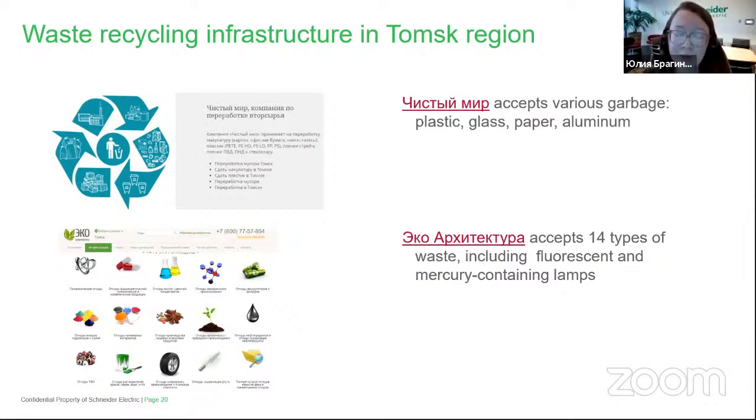And I want you to know that the fluorescent lamp is hazardous waste, which is classified in Russia as first class waste. You have to have a special contract, a special agreement, with a company which can do the demercurization, and not take these lamps to the landfill, because it can be very dangerous for the environment in this region.